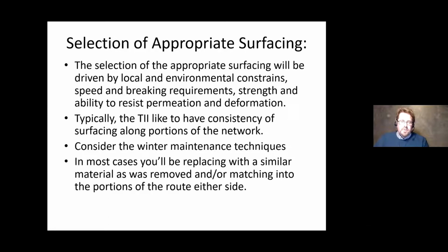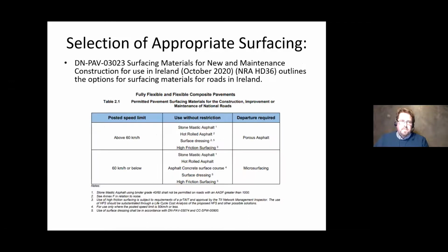Now, there will be exceptions to this, and if you can validate, I'd say you're replacing an urban environment and you want a quieter stone, you want to reduce the noise in houses, definitely look at SMAs, but be conscious of the issues that are going to be there with grip and reduced friction. So, selection of appropriate surfacing.